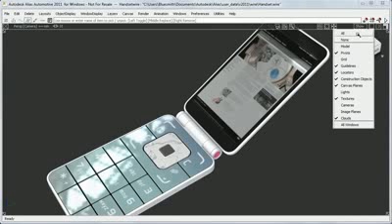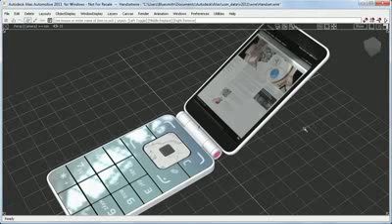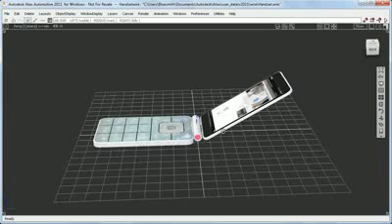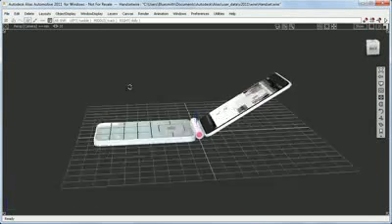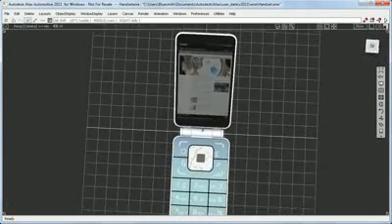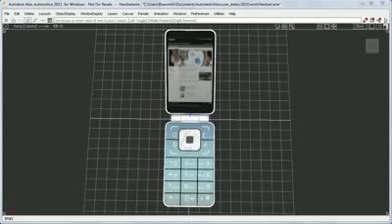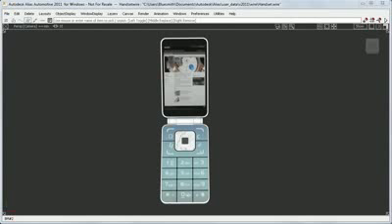If I turn the grid on for the handset model, you can see that it's been built lying on the ground plane, and that the tumbling is oriented around the Z-axis. So it's tricky for me to control the view if I want to see it in a different orientation. And this is when I would use the view twist and the azimuth and elevation tools.